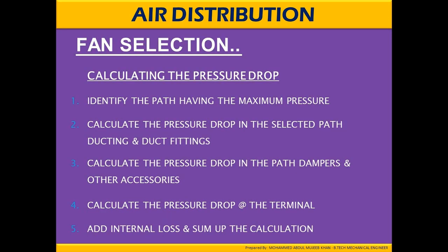Fan selection. Calculating the pressure drop. Identify the path having the maximum pressure. Calculate the pressure drop in the selected path ducting and duct fittings. Calculate the pressure drop in the path dampers and other accessories. Calculate the pressure drop at the terminals and internal losses and sum of the calculations.